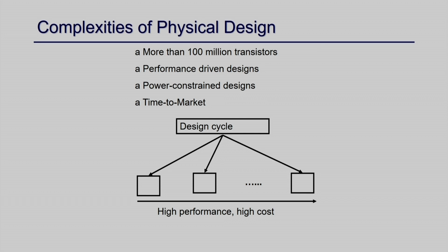Okay, so what are the problems or difficulties in physical synthesis? You can see that the number of transistors may be 100 million, 10 million, which is huge, and handling such a scale of design is not easy. Also, sometimes you have performance driven design, where you want to achieve a certain timing, your power dissipation should not go beyond a certain limit, and your area should not go beyond a particular limit. So you always have to meet a target. So this is performance driven design.